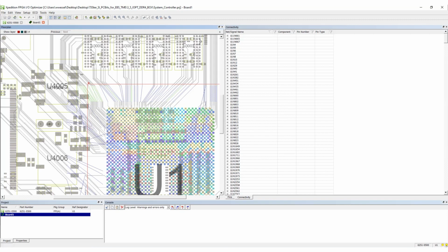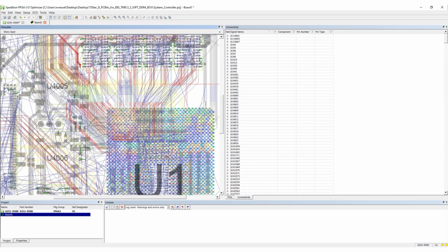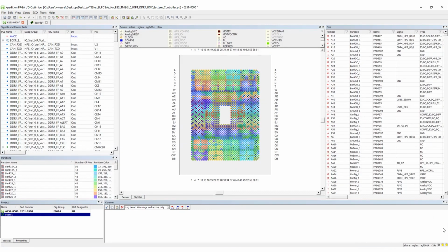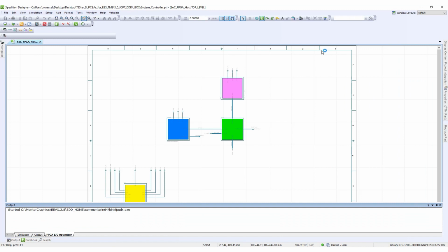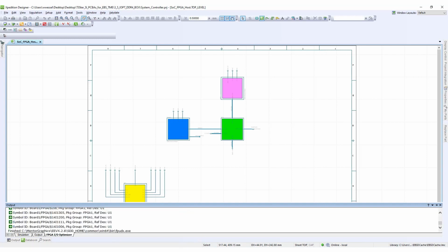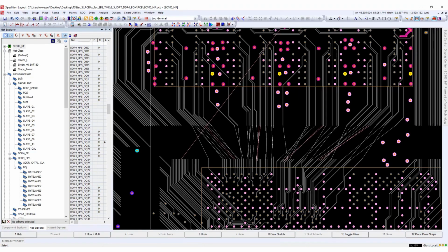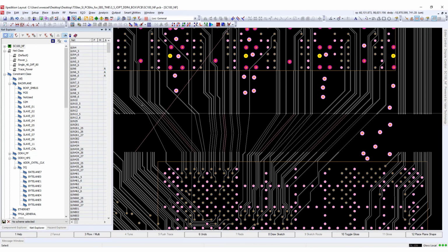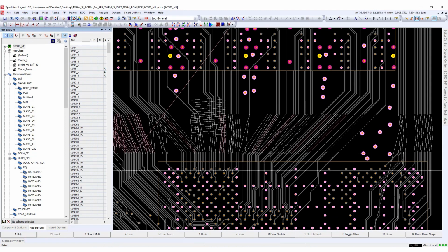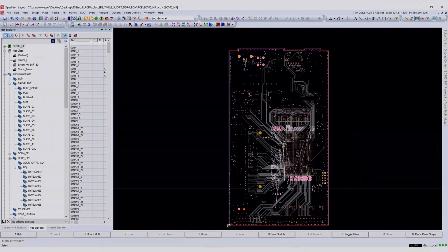The engineering change order process does not only write back data to the PCB domain. It fully supports a bidirectional exchange of native file formats from FPGA vendors like Intel, Xilinx, Lattice and Microsemi. In our case, we are using a VHDL signal source and a QSF constraint file for the pin location. ZAC can now use Xpedition routing technology to finish this optimized set of signals.